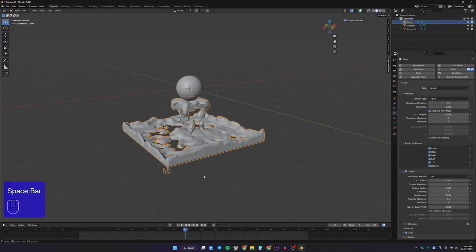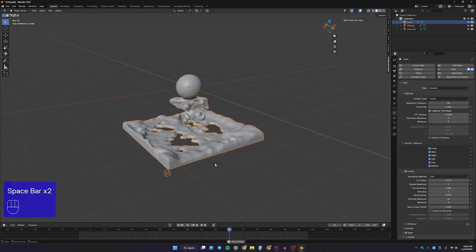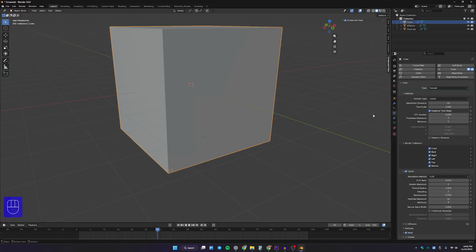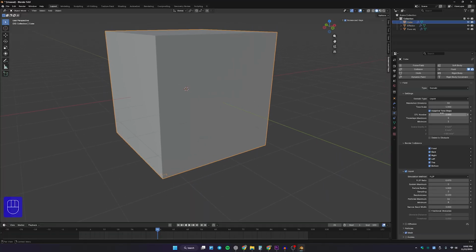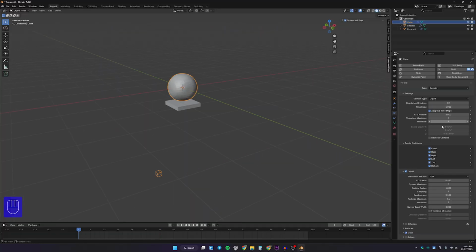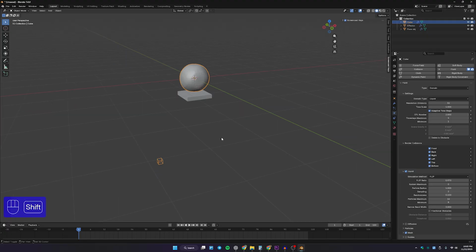And also it's really fast in calculations, by the way. So I'll undo that to my default value, and most of the time these values are working fine. So most of the time you don't need to tweak this CFL number or anything right here. If you increase your CFL number, most of the time you have to increase your minimum number in the time steps. Now if you're reducing that CFL number, you have to increase your maximum number. So with that being said, let's jump into the second part right here.